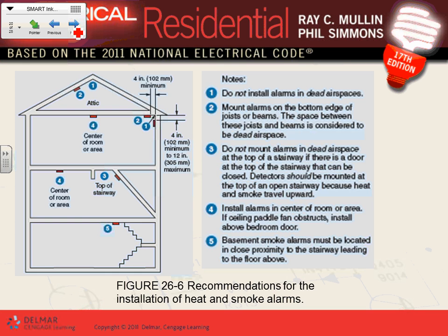No problem, Chad. Okay, now this is one of the most important things. Now we know which areas to put them in. Now, where in the room do we need to put them? In the past, guys, typically in bedrooms, if this is the door for the bedroom, you put it right in here for two reasons. Number one, it also points to the exit of the room. So you wake up in the middle of the night because of the noise, and the light is flashing, so it points directly to the location we have to exit because of fire. You can put it anywhere you want, as long as you meet this criteria, but typically you put it right close to where the door is.